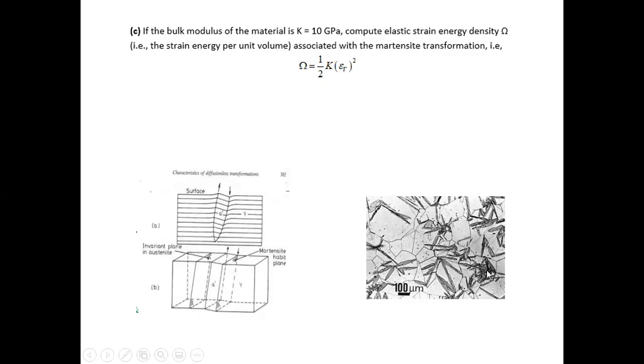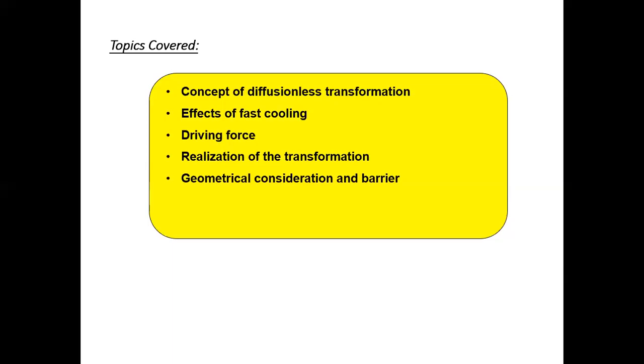These are the trace of Martensite transformations, and in particular these twinning structures, where you have a release of the very high strain energy built into the system due to the transformation. Okay, so that's basically the Martensite. I think pretty much, this is all I want to tell you about this.